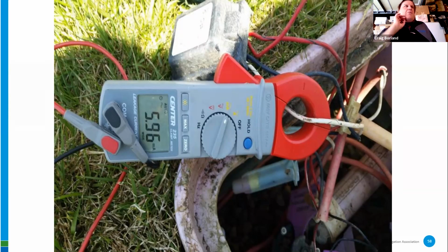So there are many classes being taught today. Manufacturers teach them. Independent organizations teach them. People like you folks teach them. There are many different classes out there. What I have learned by troubleshooting 2-wire for the past, I'm going to say close to 20 years, some more recent, a lot more of them nowadays than in the past, is that I have found clamp meter usage is great when I have a high current draw due to a bad decoder.